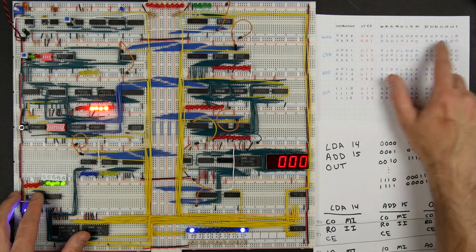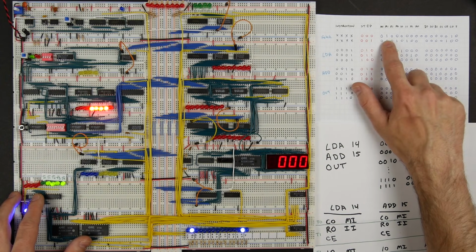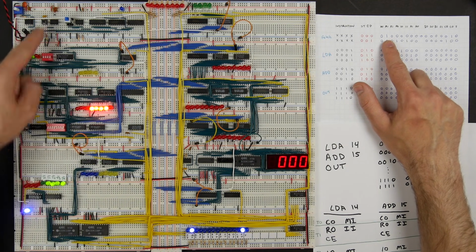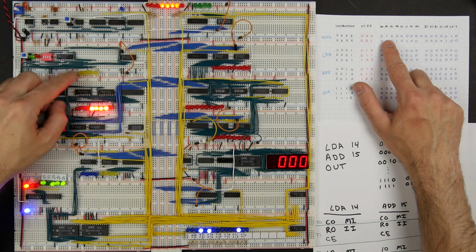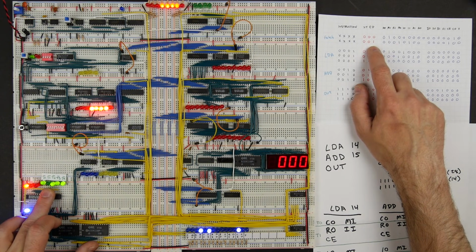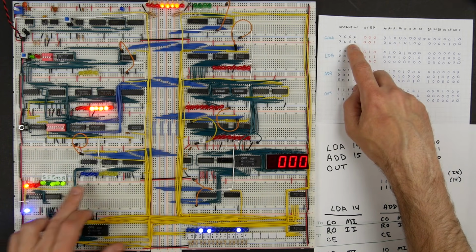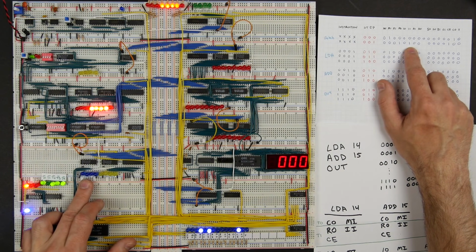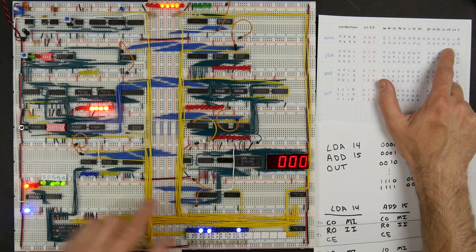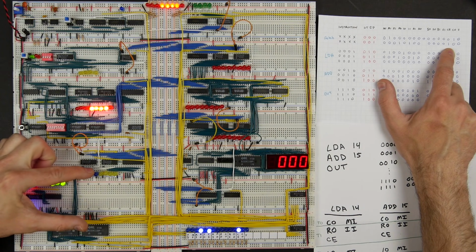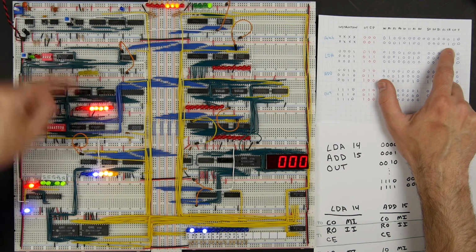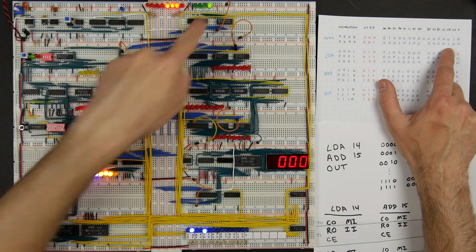For step 0, we want to do counter out and memory address register in, and so counter is 0, and we're going to put that into the memory address register. So counter out, memory address register in, so we do that. Nothing really happens. We're just putting a 0 there. But now we're at time T1, and so step 1 here, again, doesn't matter what our instruction is. We're going to do RAM out, instruction register in, and counter enable. So it's going to take the contents of RAM, put it into the instruction register, and also increment our counter. So we'll go ahead and single step that with the clock, and there it is. That moves that there, and our counter is now 1.